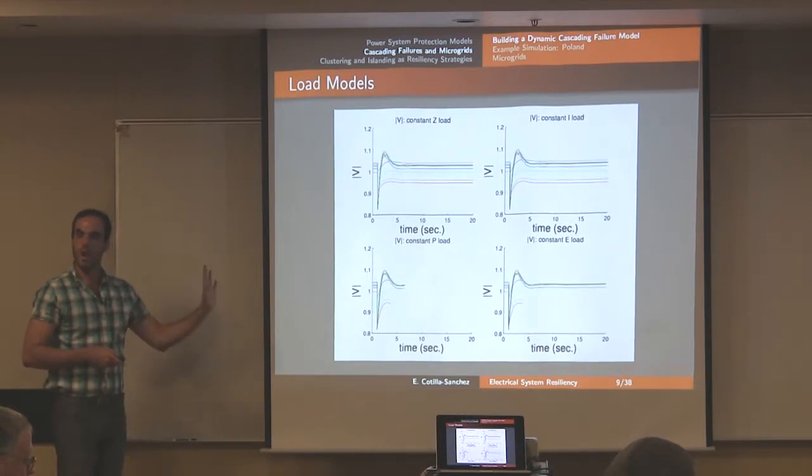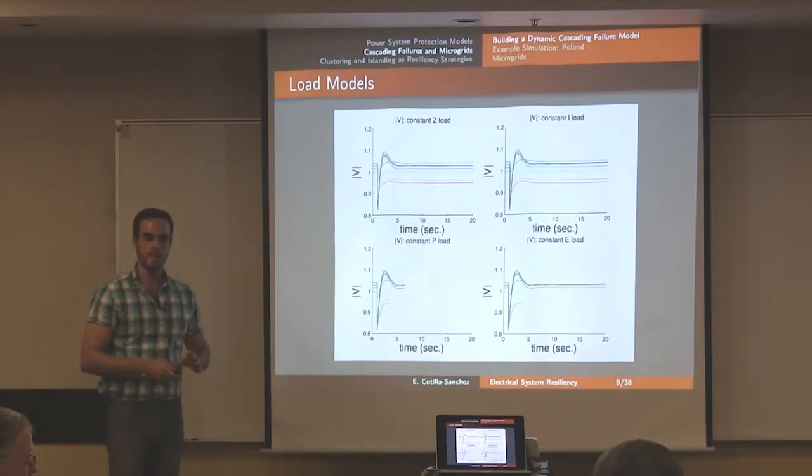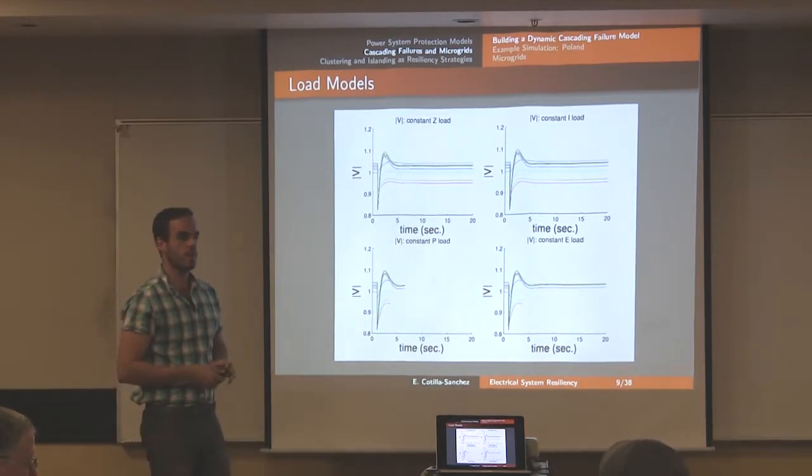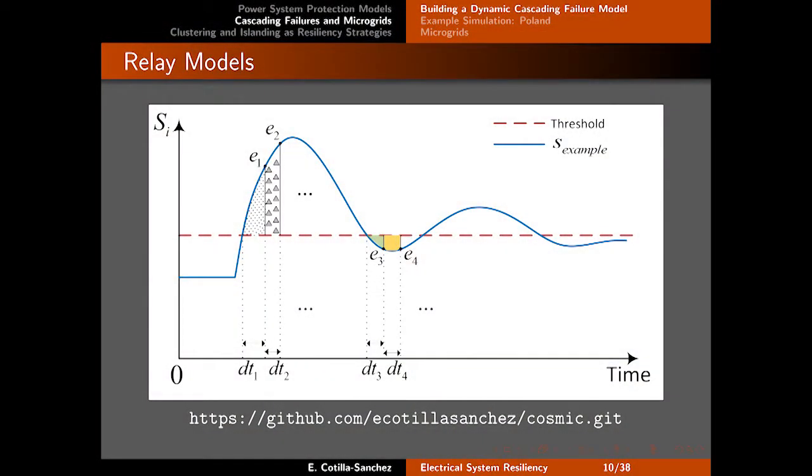So load model, I'm not going to put a lot of emphasis on that later in the presentation, but it's one of the other ingredients that sometimes we might really have to highlight for our time domain simulation. Protection devices are also very tricky sometimes. It's hard to find a baseline of how we are going to model that type of relay, and how we are going to model the delay in all our relays.